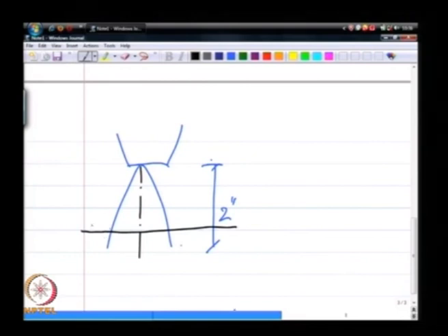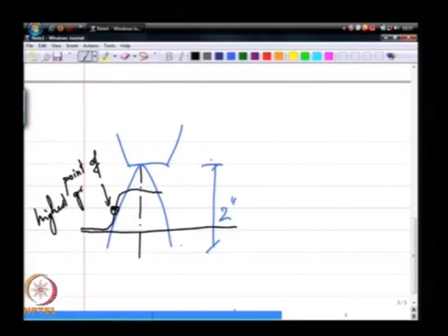So, whiteness as in a grayscale, and it goes from nearly pitch black on the outside of the spray to where the liquid drops reflecting light back towards the camera look whitish at a higher grayscale number, and when I plot that quantitatively I get a plot that looks like this, and from these two inflection points I can get the width of the spray at this axial location. So, typically what is done is that you could get the width at a couple of different axial locations,